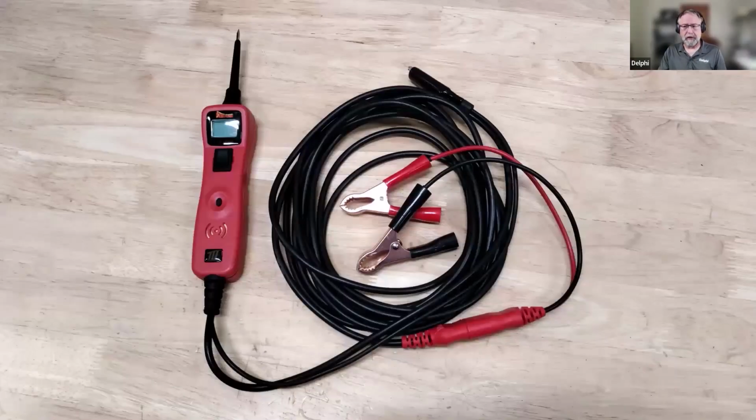People spend a lot of time slagging the power probe, and I know why. And the problem is not the tool itself. The problem is a lack of education, because people go nuts with the power and ground switch that's on this thing, and they inject 12 volts and grounds into places where they shouldn't because they don't understand what's going on, and then they let the smoke out of the box. And this sometimes leads people to say power probes are bad.